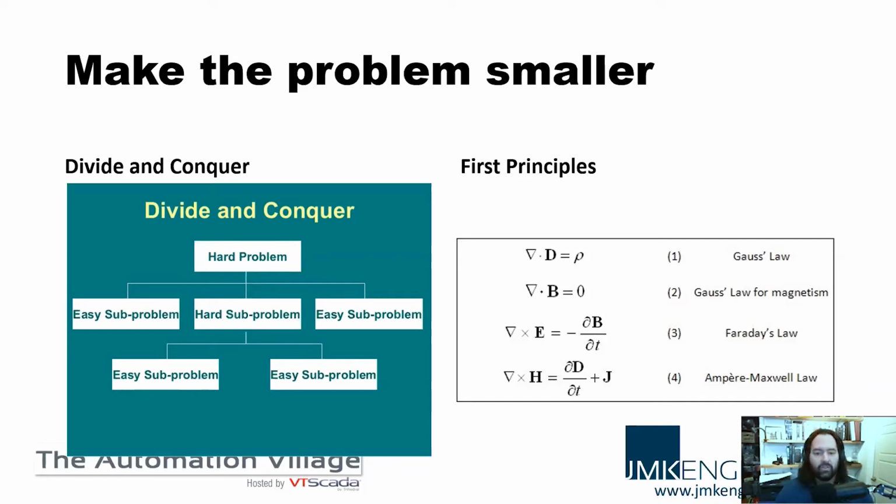You can think of a single circuit with a bunch of elements as a bunch of independent systems. If you're monitoring a sump pump, for example, the circuit itself is designed to turn on a pump or create an alarm if the water level's too high. The circuit doesn't care how that contact is made up. It could be a float switch, it could be a contact off of a level sensor, but it's just a black box. It's just a level-is-at-this-height kind of contact.